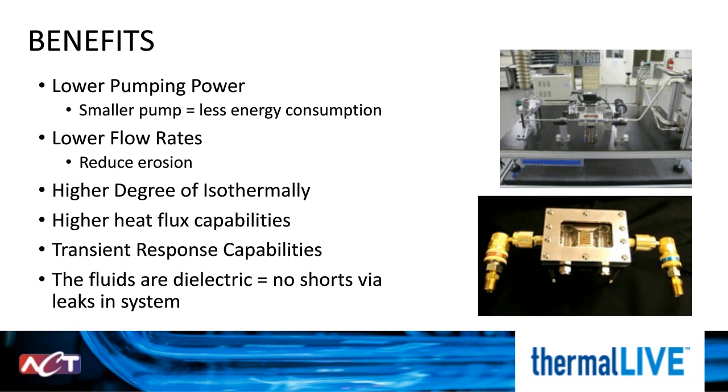Now, by utilizing specific heat in single phase, you are raising the temperature of your fluid as you absorb the thermal energy from the component. This means that every component down the line will see a different fluid temperature than the one before it. But with two-phase, by setting the saturation temperature and utilizing the latent heat of vaporization, your fluid remains a constant temperature, which means that every component will vaporize at that same temperature and will see the same temperature down the line.